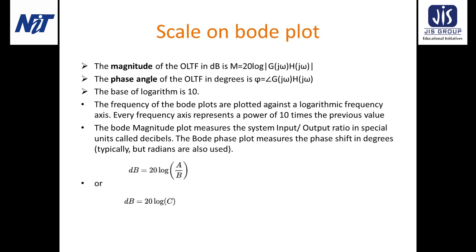And in the Bode plot, the phase shift is actually measured in degrees, but radians can also be used, and for the magnitude plot we will convert it into dB by multiplying 20 with the log of the value. So, these are the scales on the Bode plot.